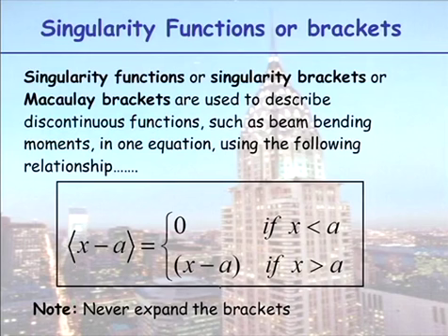The way these brackets work is, if the term in the bracket is negative, so if x is less than a, we set that value to 0. And if it's positive, it just becomes a normal positive value. So when you have these brackets, you never expand them. Because if you expand them, you remove the ability to turn them on and off, to make them appear 0.